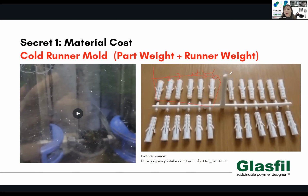Typically we will do it very evenly and symmetrically. So you have set number 1, set number 2, set number 3, and set number 4. So if any suppliers were to ask you, you will need to tell them, I have a mold, and this mold has 6 times 4 cavity, which is 24 cavities.